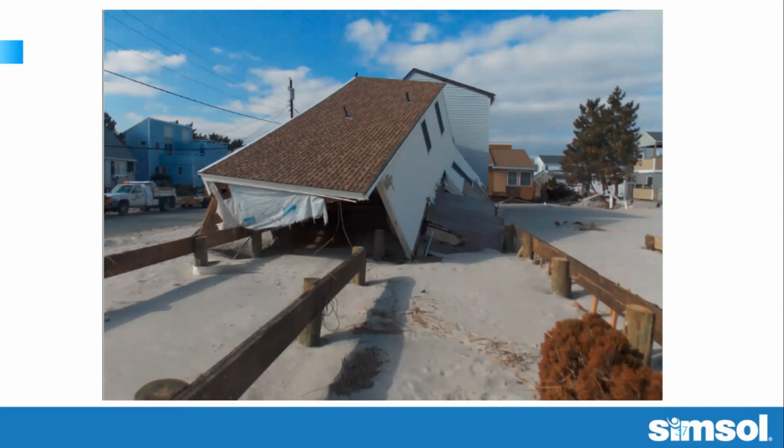So the surge flooding would have come from behind me in the photograph, impacted the front face of the house, and pushed it off of its foundation. There's a couple of things that I see as well. There's the accumulation of sand built up, and that's one thing that would tell me that it's water. Another thing that I'm looking at is the neighbor's house throughout the surrounding area. There's not one shingle off. No matter what a plaintiff attorney will tell you or a public adjuster will tell you, wind is going to affect everyone in the neighborhood, not just the particular house that he or she represents.